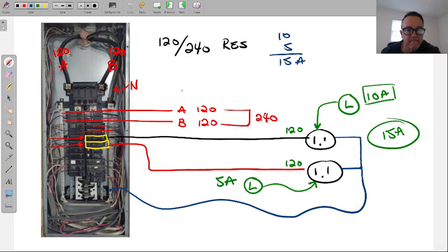Yeah, this is a new house. The wire is hot. First of all, the wire being hot on an extension cord is not a worry. We don't like extension cords, but that's not the concern. If the wire is hot in the panel at the breakers, then that's a worry. You maybe have way too many things plugged into that circuit. But heat is normal. Heat comes from current. That is okay.